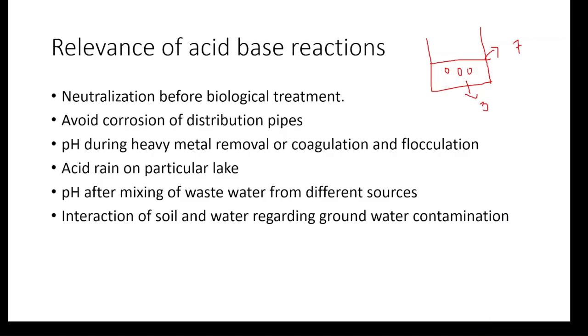It is very acidic. It contains a certain pollutant and this bacteria is active at pH 7. So we need to do some acid-base reaction. We need to add some bases to increase the pH to 7. So how much base do we need to add? That comes from the acid-base reaction.